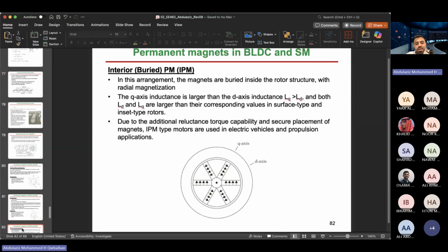The last type of permanent magnet is the interior one, which is my favorite. Instead of having the magnets on the rotor surface, just put them inside, put some weird shapes like a star shape, and fill it with magnet. Some people put a zigzag shape, similar to the other shapes of the stars. Some people put circles inside. So the floor is yours.